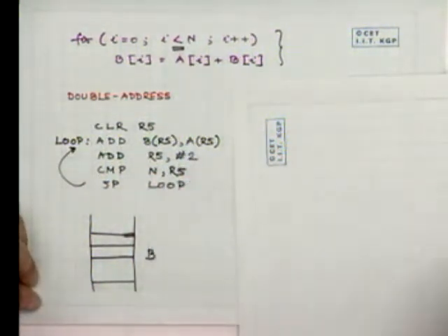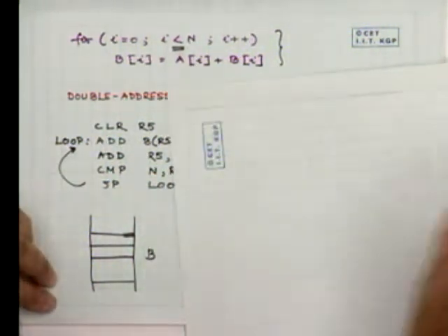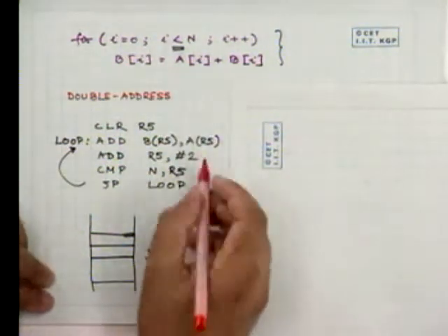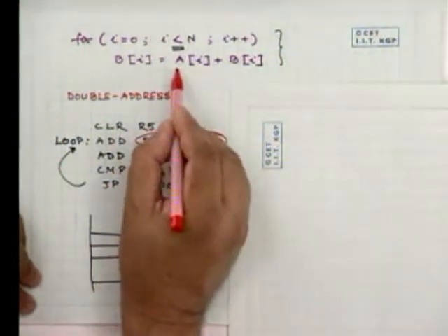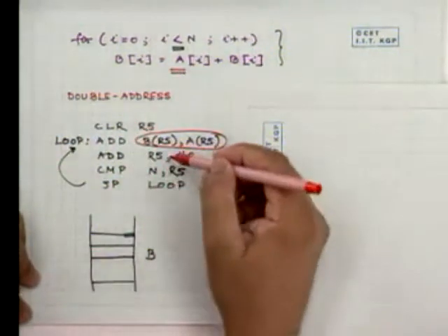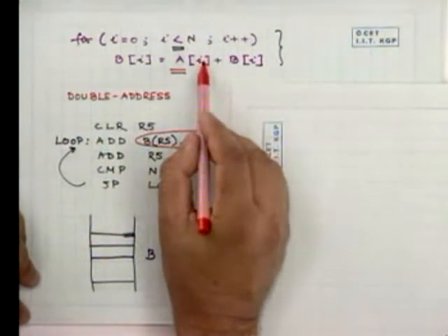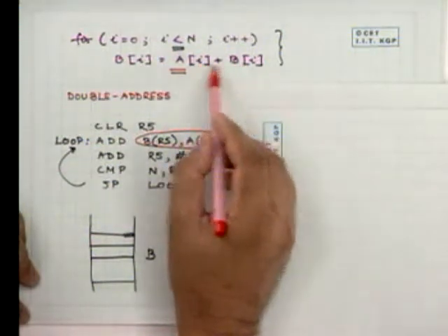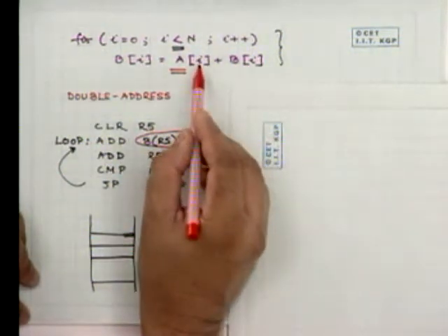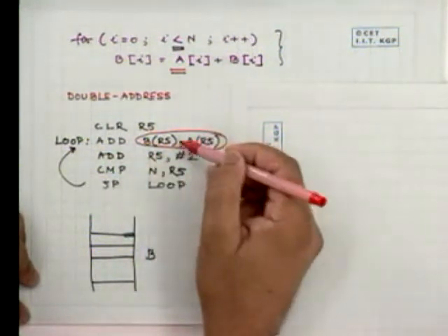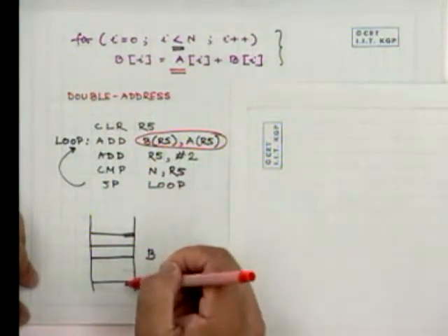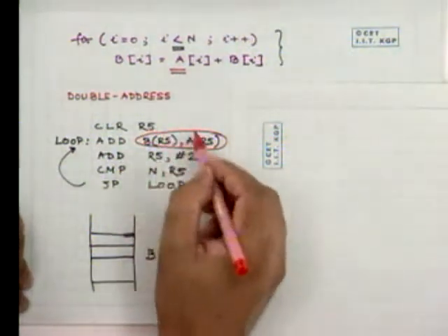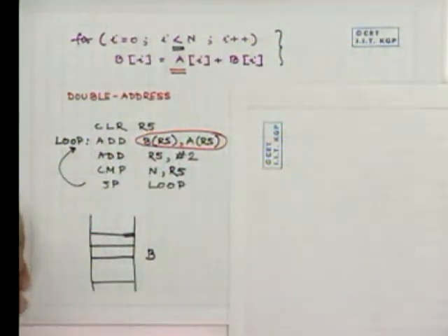Here you see that indexed addressing is very helpful in such cases where I am trying to take the contents sequentially. Now that I can be incremented by any value, therefore if you are going to take at regular intervals the content of memory locations, then indexing is very fruitfully utilized, right?